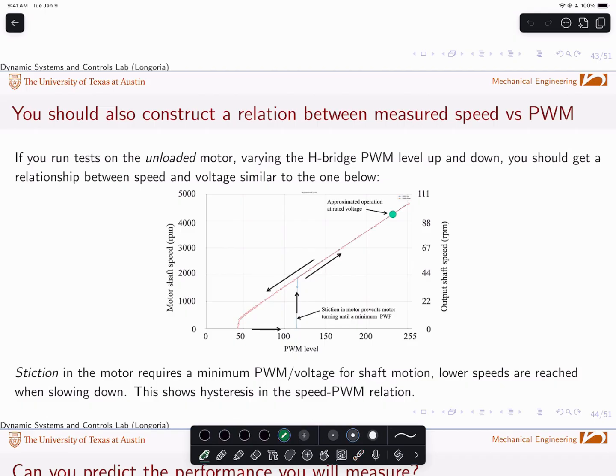by the way, something to be aware of is, imagine you've got that motor and you've got the shaft of the motor, and then you've got the little gear head there, and then here's omega O output, here's omega M. Since the encoder is actually on the back end of that shaft, here's where the speed is being measured. So you're actually measuring omega sub M. You're not measuring that output, which is much slower, by a ratio of 45 as we've measured. So the motor shaft speed is what you're measuring, not the output shaft speed.